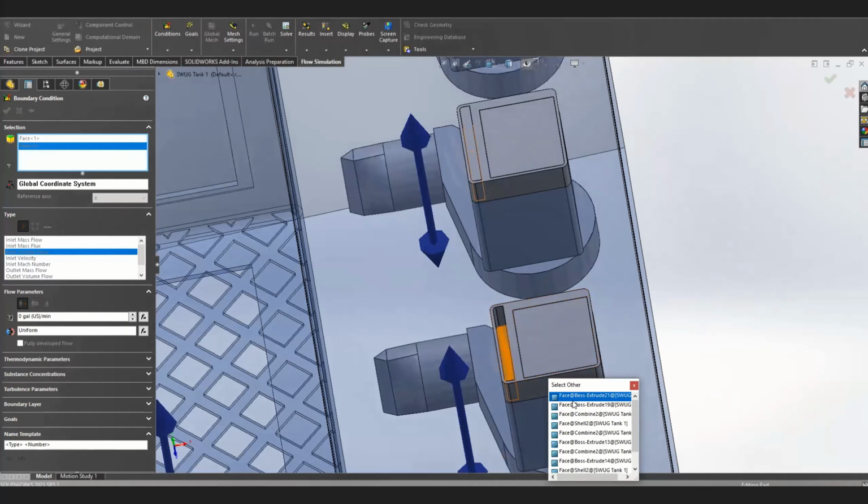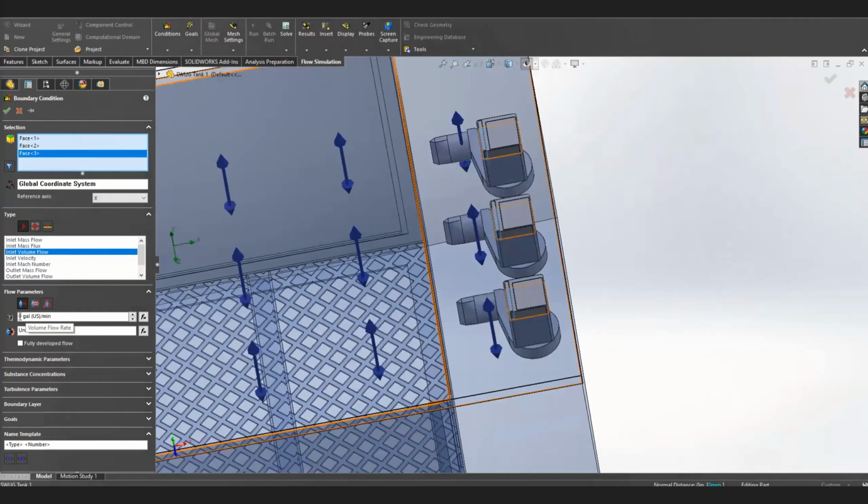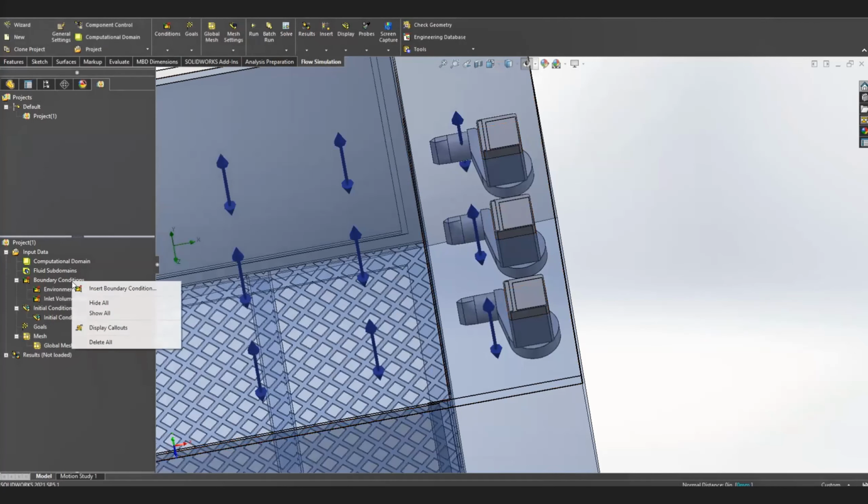It's a lot of hassle, and it's not really what I care about in the study. So what I'm actually doing is essentially telling it it's pushing 12 gallons per minute of water into the tank, and at the same time pushing 12 gallons per minute out of the tank so that the water level isn't ever changing. It's essentially simulating circulation without me having to worry about moving around with a propeller or anything.